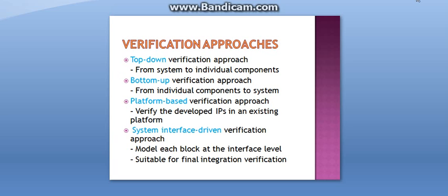There are some approaches in verification. They are the top-down verification approach. It is from system to individual components. It contains system specification, then system design. In between system specification and system design is system level verification. In system design, the hardware IPs library and the software IPs and RTOS library are present. After the system design, hardware-software partitioning is done. Then synthesis, chip plan and design with the netlist verification, and then functional verification, timing verification, and the device test.